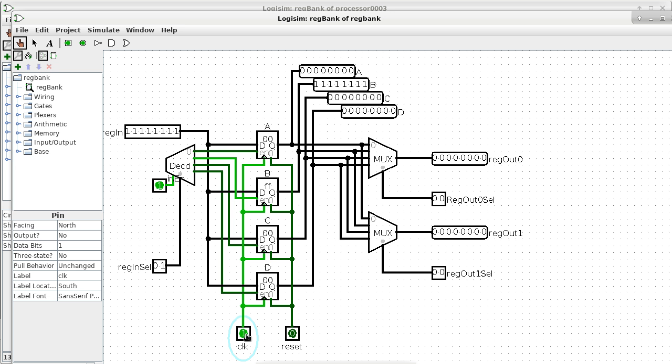Okay? So I call this a register bank because it is a collection of multiple registers. And these registers are quote unquote software accessible registers. So your code, your opcode can directly say, I want register A here, I want register B here, I want to update register C over here, and so on. So these are software accessible registers, whereas the other registers, you really don't have direct access to those. Okay? All right, so that kind of explains how to update a register.